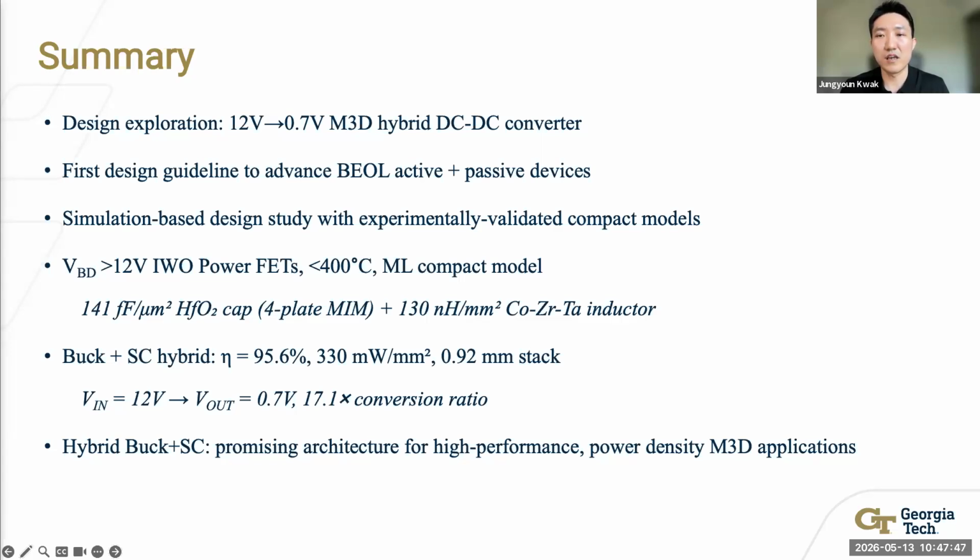Third, we built and confirmed a machine learning compact model for indium tungsten oxide power transistors. The multi-layer perceptron-based Verilog-A model correctly matches measured IV data across the full 0 to 12 volts range for both E and D mode devices.